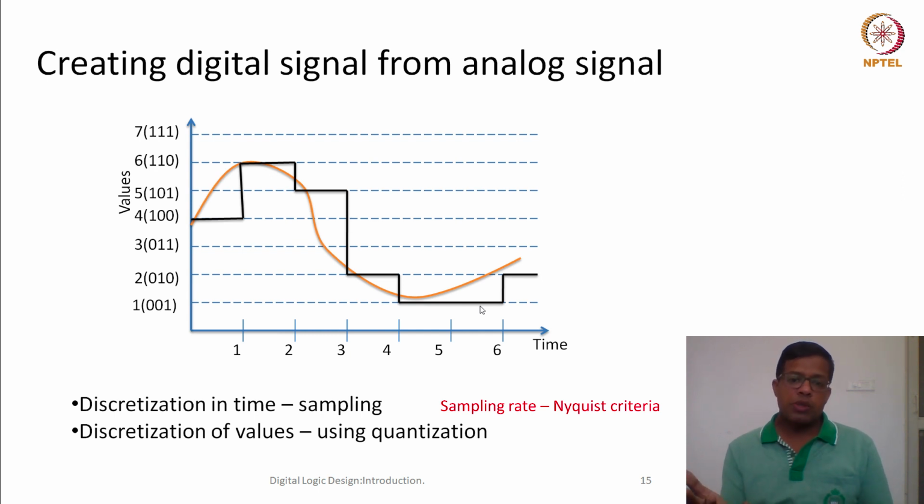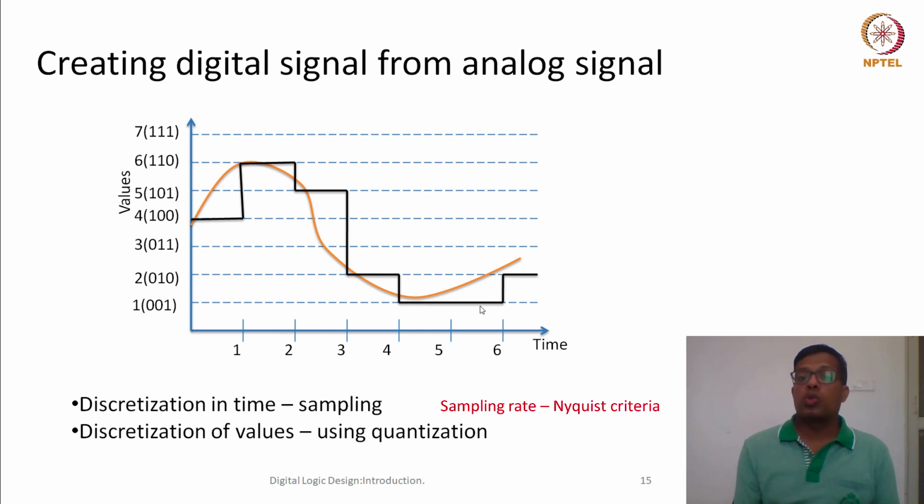It has been proved that if the maximum frequency of a signal is f, and it is sampled at 2f frequency, then we can always regenerate it without any loss of accuracy. So if our sampling rate is fast enough, we are sampling in such a way that all the minute differences are captured, then we would be able to reproduce the signal.